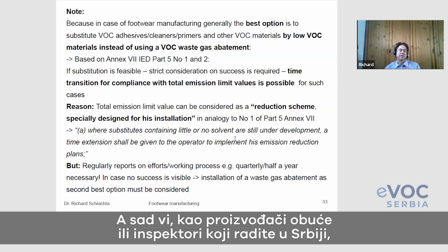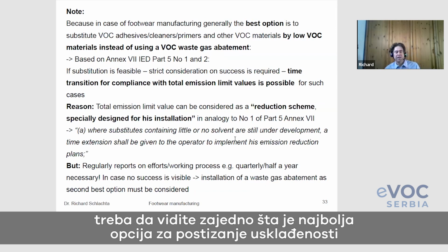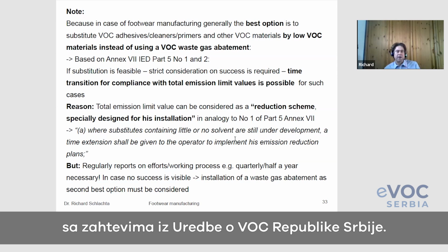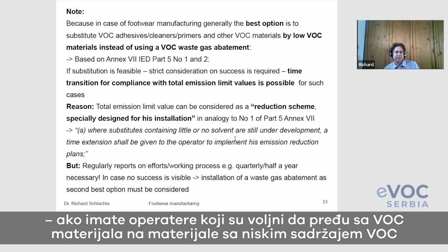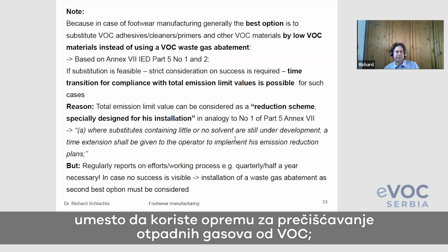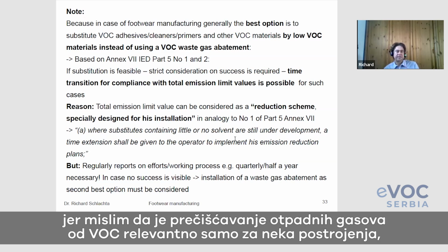Now that you establish the VOC decree in Serbia, and you as a footwear manufacturer, or the inspectors who are working with the footwear manufacturing companies, think about what is the best option for compliance, I strongly recommend you keep in mind, if we have operators that are really willing to change from VOC to low VOC materials, to do so instead of using a waste gas abatement, because I think waste gas abatement is only relevant for certain installations.